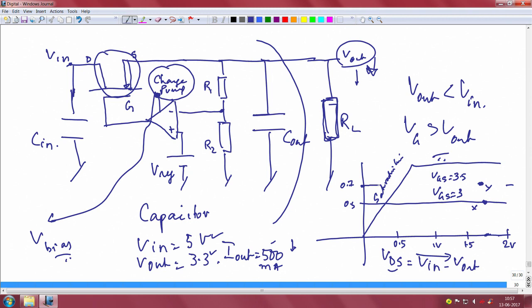So, that is point Y. So, here you have to give the additional VGS so that it actually moves. So, look carefully, you have not violated this voltage drop across VDS, but you continue to keep it exactly at the 1.7 that is required.